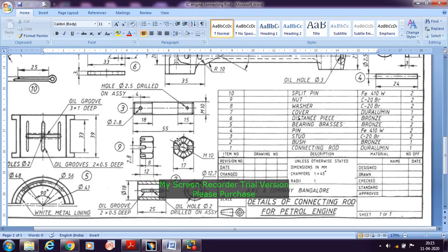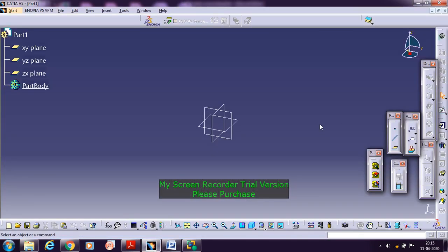Now we need to construct, for this we need to go with the sketching. We need to construct the hexagon for 10 mm dimension, and then we need to go with the thickness 12 mm here. That I will do now. In this case, it will be seated in the front view direction, or in the side view plane. So now I'll be using the side view plane.